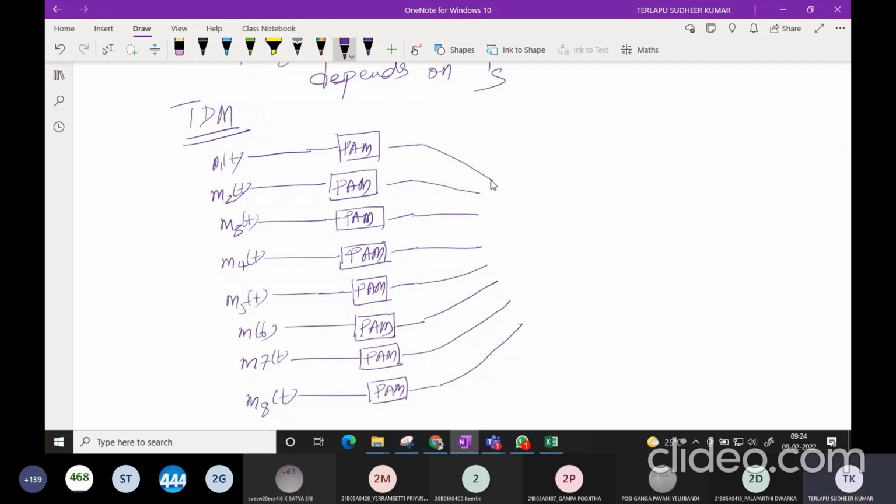So here I have a switch, and that switch is operated with a commutator. If you observe carefully, from signal 1 to till 8, one complete cycle will take Ts time. Keep that in mind. So now this is passed through the channel. This multiplexed signal is passed through the channel because we have only one channel.